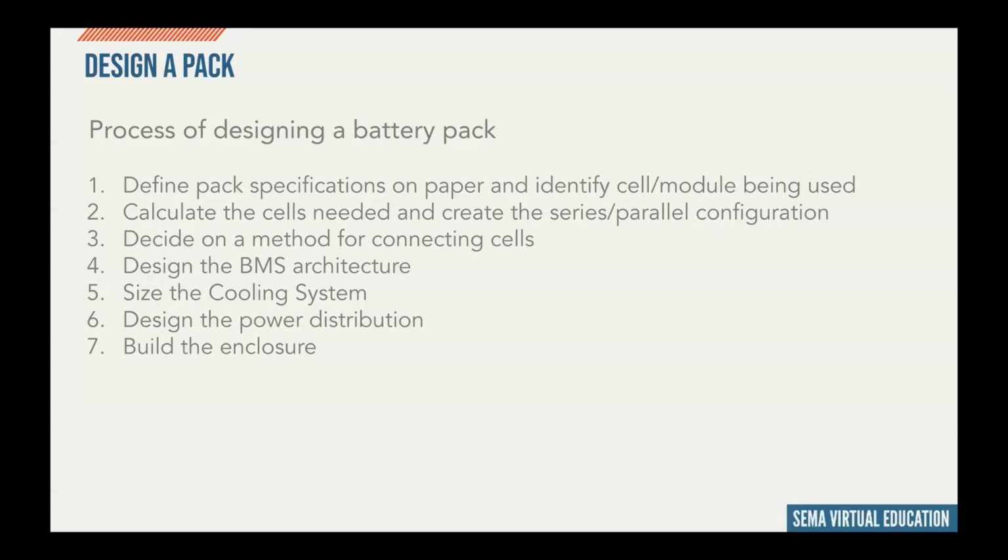There are many factors to this, including considering the cooling system integration and the BMS, but this is a very essential step because it will tell you how many cells are needed, and therefore a space claim, and the rest of the components can be designed together and then an enclosure at the end.